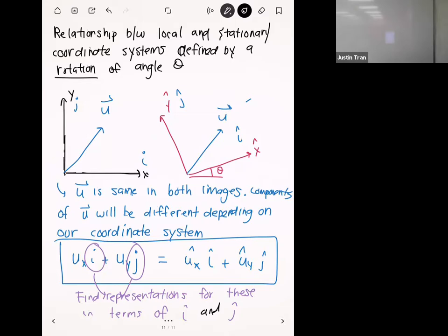In this model, it's the actual vertical direction. But it can still kind of move in an x and z direction. The reason I did that is because I was a little bit worried that the bridge might be a little bit too stiff in 2 fixed conditions, but in reality, it's actually fine. So it could have been 2 fixed conditions there. But it was also a good chance to show you guys that you can do a roll with stuff like that too.